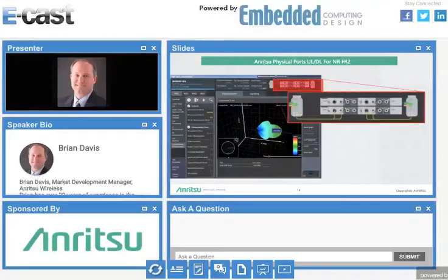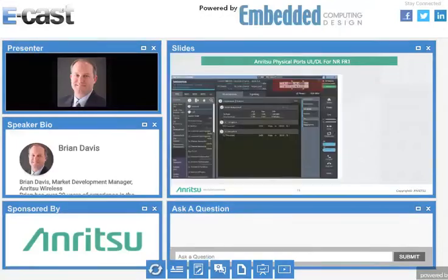You'll always get, on the top right as well, how you're physically connected to the equipment. So there's our millimeter wave up converters, our 28 gig. We've also got 39 and then a multi-wideband that covers all of the millimeter wave frequency ranges. You'll be able to set the physical ports that you want to use in the front panel, and then you'll always have the GUI there telling you how you're supposed to be connected as the software is expecting, or how you've set in the background.